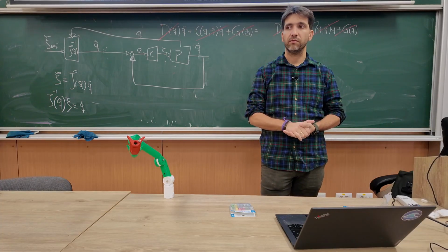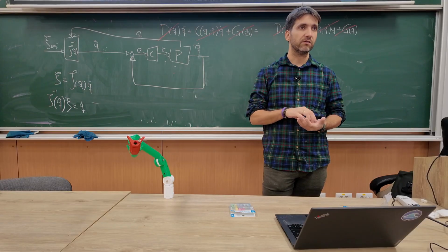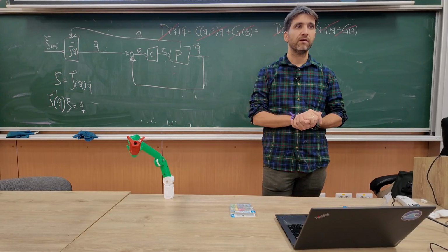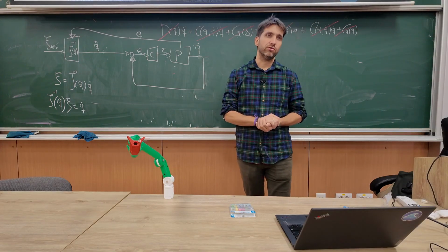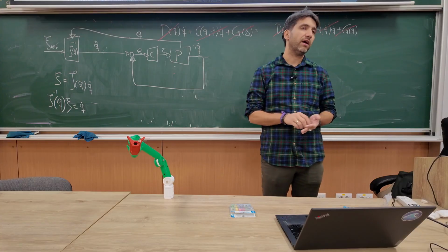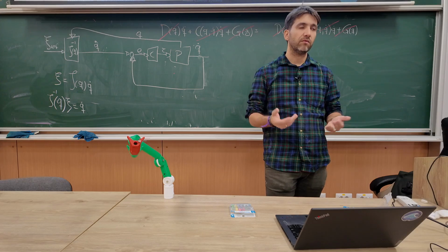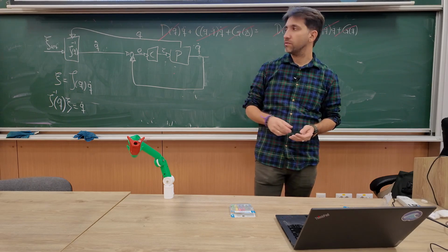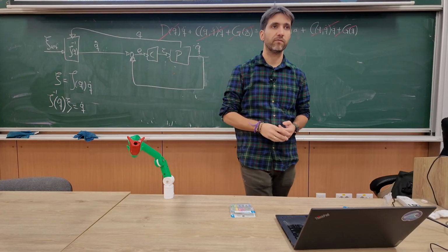You can have error accumulating and drifting and things like this. But I know the position from the process. Typically, we know the position of a joint. If we don't know it and we only know the velocity, then yeah, we should integrate that to get the new positions to update the Jacobian.